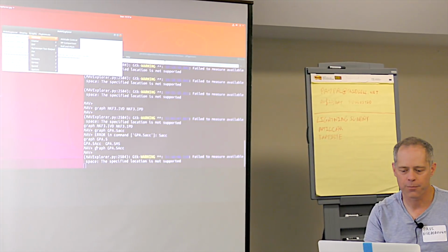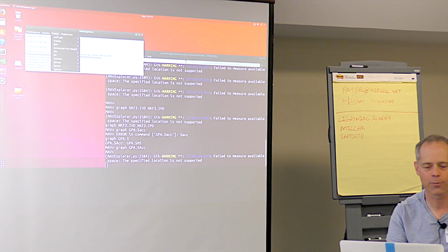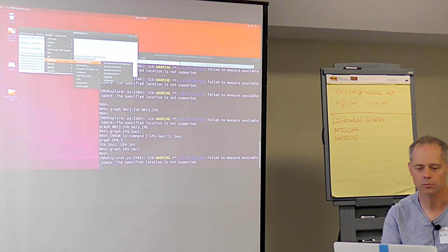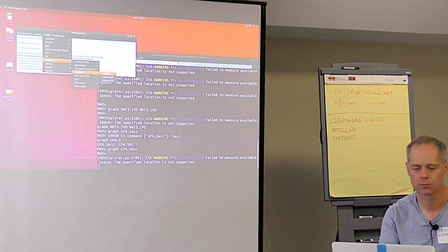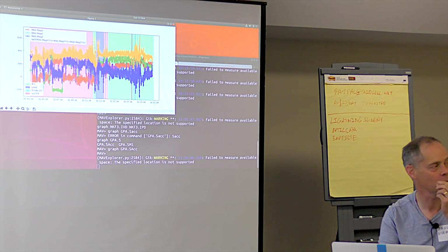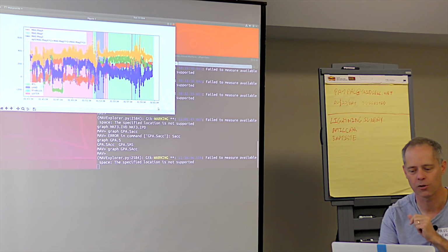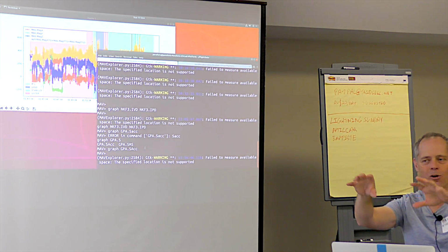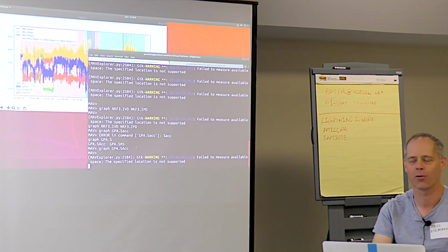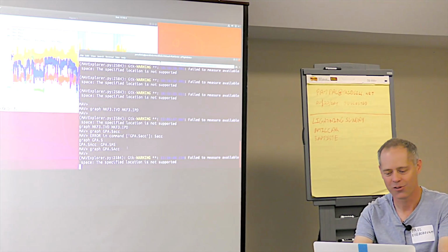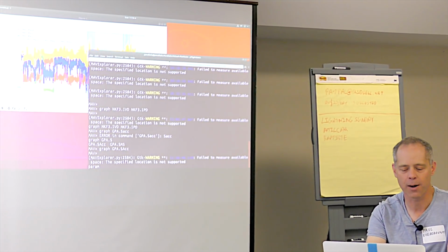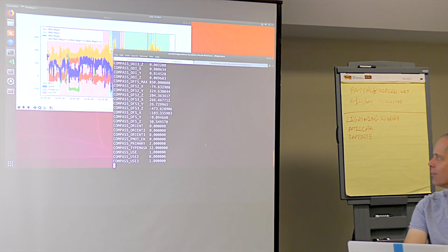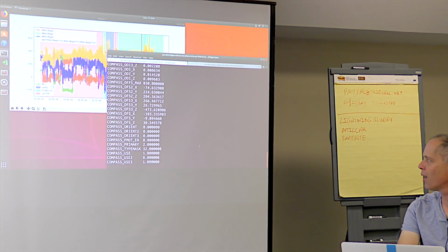Okay, so if I'm looking for evidence of problems with the magnetometer, we have a pre-packaged graph here under sensors. We go to compass, and you need to make sure that you're actually using the compass that you think you're using. I've been caught out this way, looking at a log provided online with an extensive analysis, and then somebody pointed out to me, oh, by the way, they were using the other compass. So in this case, you can check the parameters in the log. And here we can see right at the bottom that they're using compass 1 and compass 3.